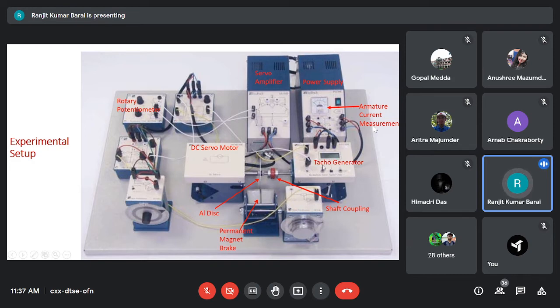See, here the tacho generator we are using as a sensor, because we have performed some very crude signal conditioning. By design, this tacho generator has been made a linear device. It's characteristically linear, but to prevent some noise from coming out of this measurement, we have already used some filters.